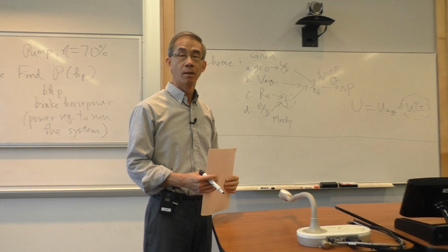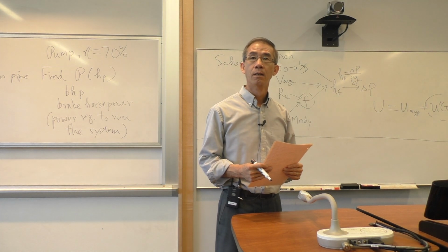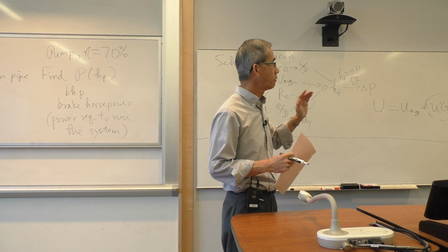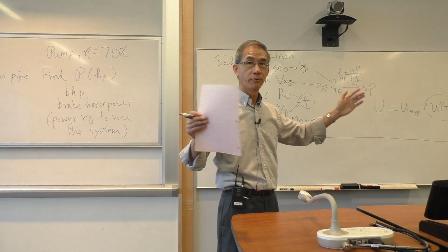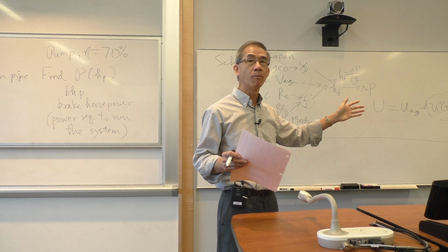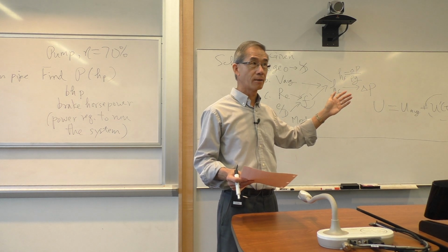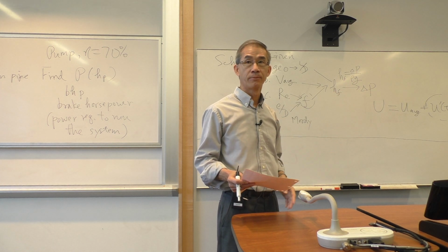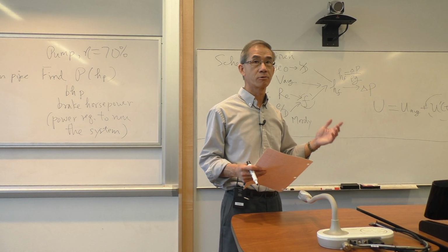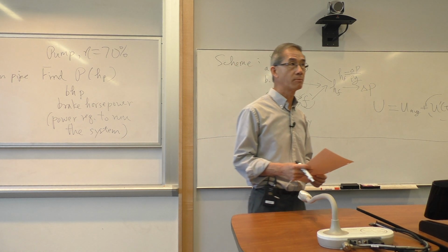So like the previous one that we did on the homework, the ideal system? Say again? The previous one we did on the homework where we didn't account for minor losses? Yeah, all those are just not idealized, but for a horizontal pipe with nothing in between the inlet and exit, no valve, no elbow, all I'm doing was shear frictional losses that are accounted for by the Moody diagram. But no flow system ever do that. You always have the valve to control the flow. So we start simple, but now we're adding complexity to make it more realistic.